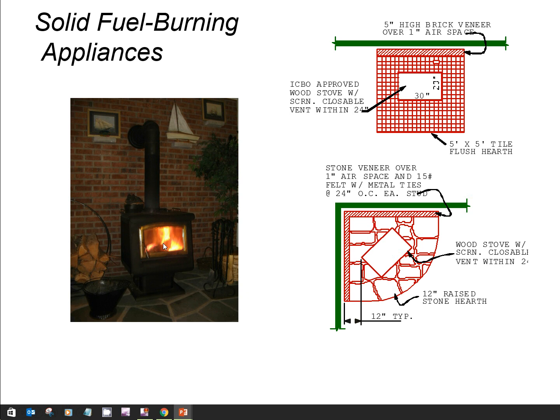There are pellet stoves that burn wood pellets that you load into a hopper. And then there are still coal burning stoves available, or any combination of those things. But they do need clear space from a combustible wall or a non-combustible wall, and then the pipe going up into the chimney. There's very specific sizes and spaces that you need.